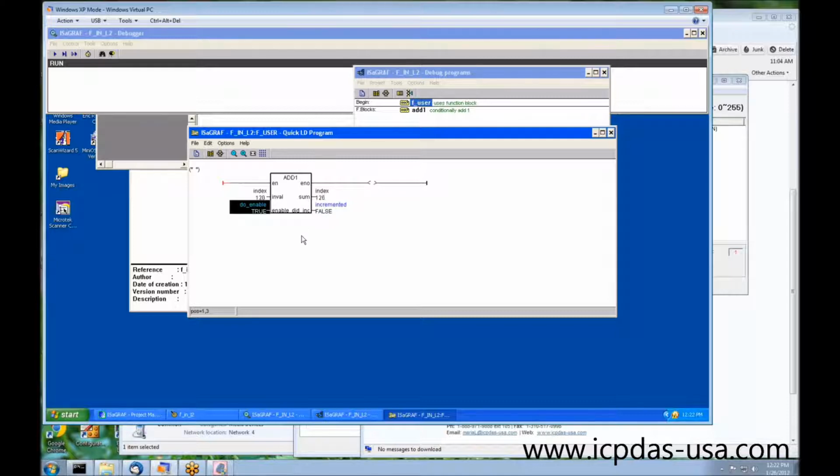Now, you might think this only executes once, but in ladder programming, each cycle of the PLC executes every program in the begin area, and in every program it goes through every rung until you hit a return or a branch or something like this.